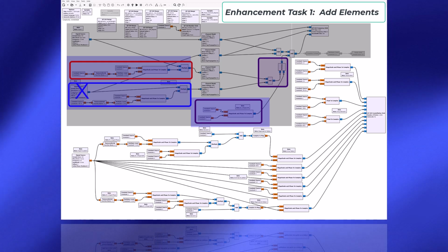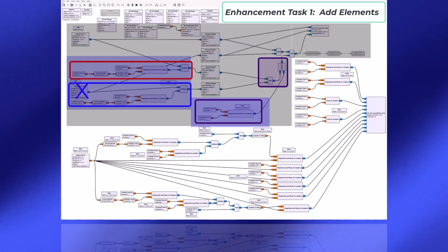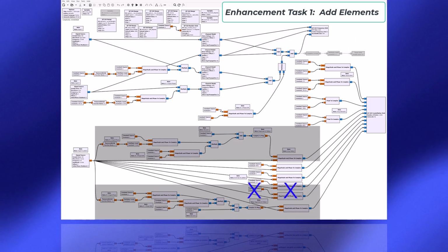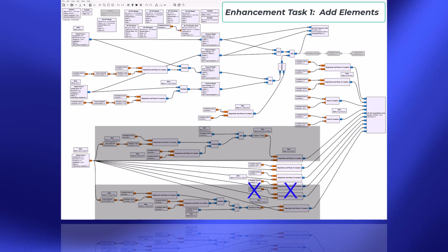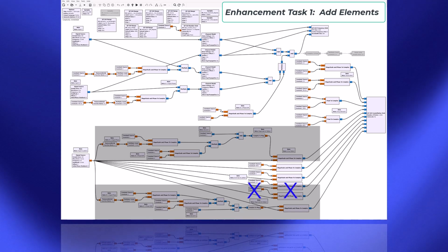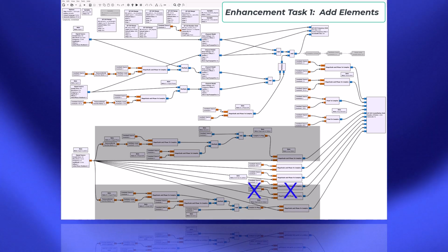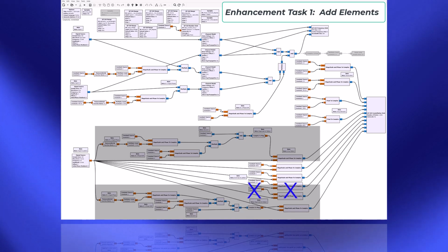Two additional collections of blocks in the flow graph are used to calculate the array pattern using the ideal inter-element phase shift and the array pattern using a quantized version of the inter-element phase shift that will contain some error due to the lower precision used in the quantized version.